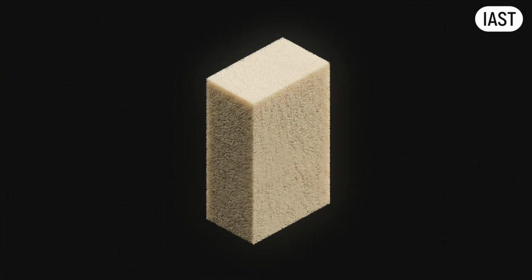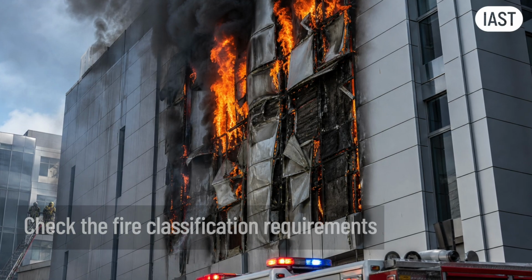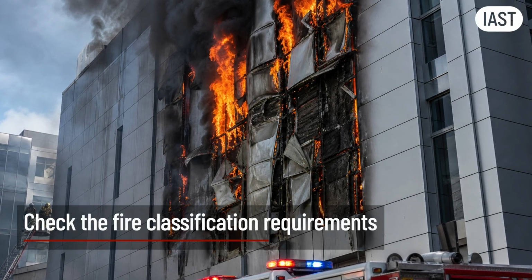But before you make that substitution, check the fire classification requirements for your building. PIR has limited combustibility, meaning that it's still combustible. And every layer in the external wall carries a classification, not just the insulation. One non-compliant material can compromise the entire system.